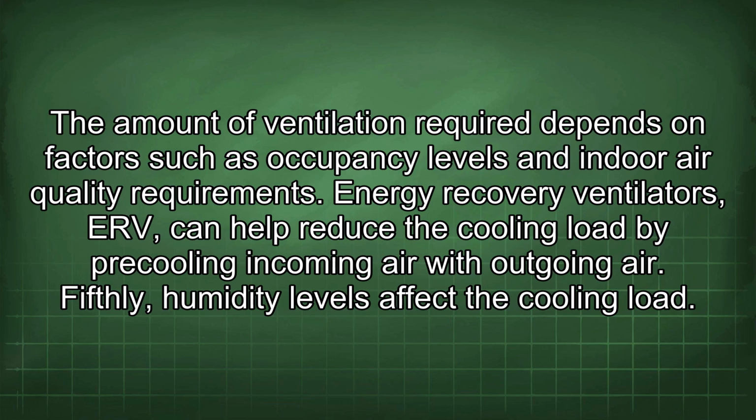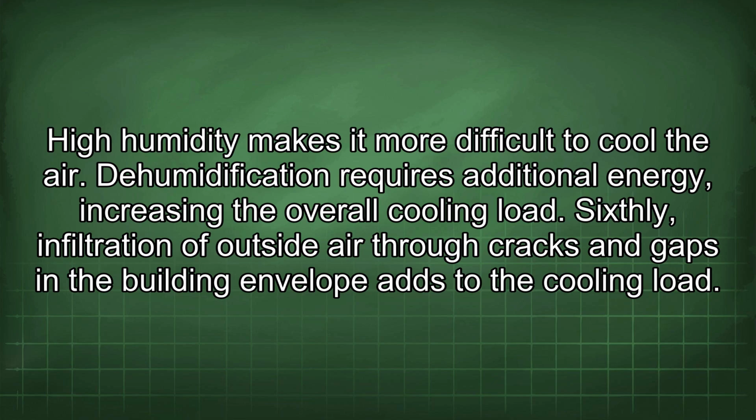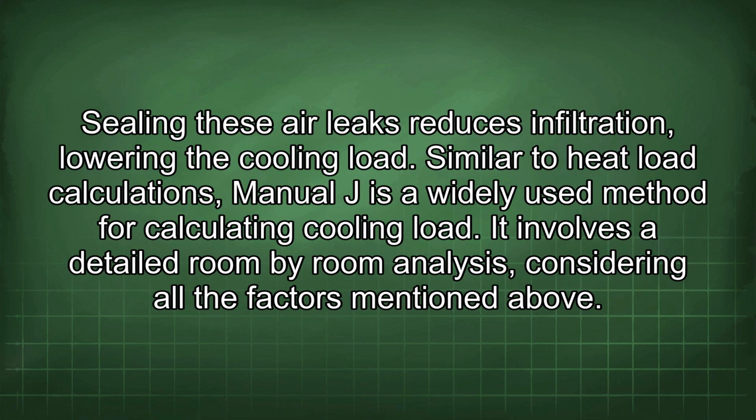Fifthly, humidity levels affect the cooling load. High humidity makes it more difficult to cool the air. Dehumidification requires additional energy, increasing the overall cooling load. Sixthly, infiltration of outside air through cracks and gaps in the building envelope adds to the cooling load. Sealing these air leaks reduces infiltration, lowering the cooling load.